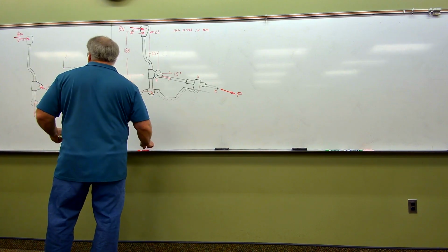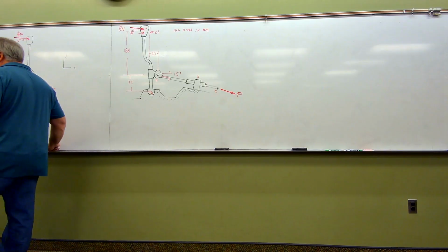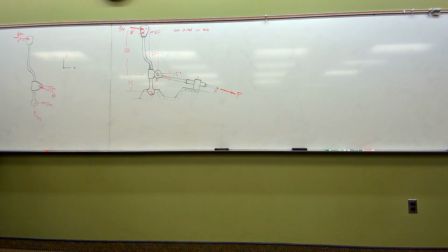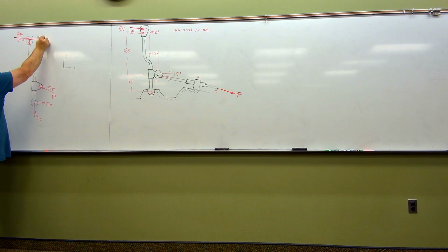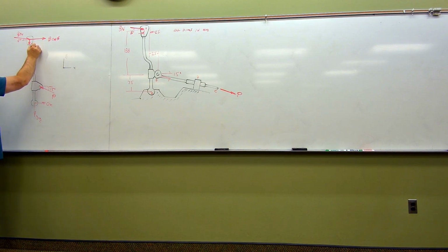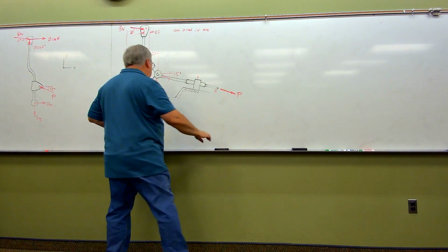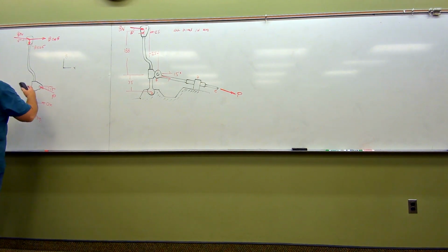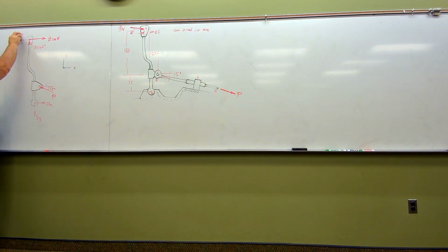Well, I think before we do that, let's do the following. Let's resolve our forces. Because here's where we gotta use Varignon's theorem. If we're writing a moment equation, we gotta use Varignon's theorem. So if I resolve this force here, this 8 Newton force, into its x component and its y component, first of all, tending positive x, tending negative y, I can slide it and anchor it right here because I know where dimensions are right here. So I'm gonna have a force going down like that, a force going over like that. This one here is gonna be 8 times the cosine of 5. This one here is gonna be 8 times the sine of 5. And I know I'm going fast through that, but we've seen this now plenty of times. So once I resolve the force, I get rid of the original force. I no longer need it.